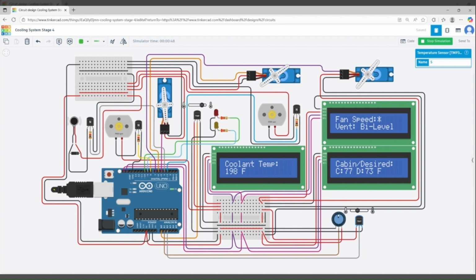All right, so now, we can see that our compressor's on over here as well. So let's take it up so it's fairly warm. So we desire it to be 83 degrees in the cab. Our cutoff valve is also going to open to let the heat through the heater core, the coolant through the heater core.